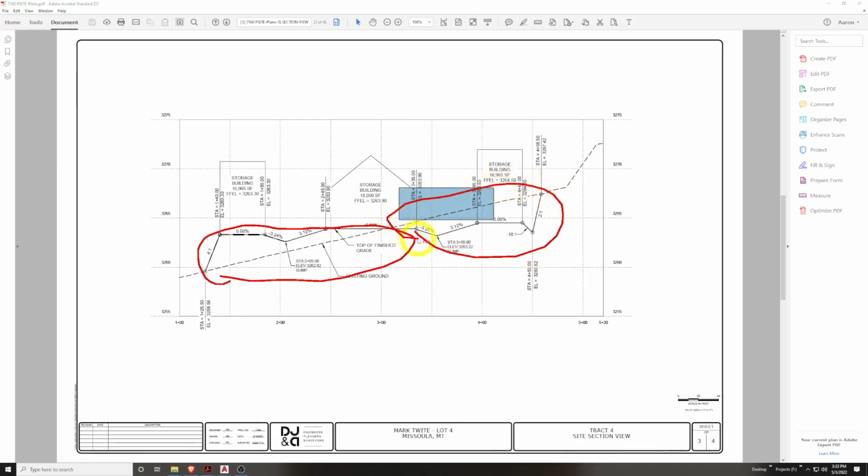My design is below my existing ground. So they balance these two little areas in here, balance each other out. This being the cut, the fill, and then this being the cut scenario. So these two areas balance each other out in the simplest sense in this way. Okay.